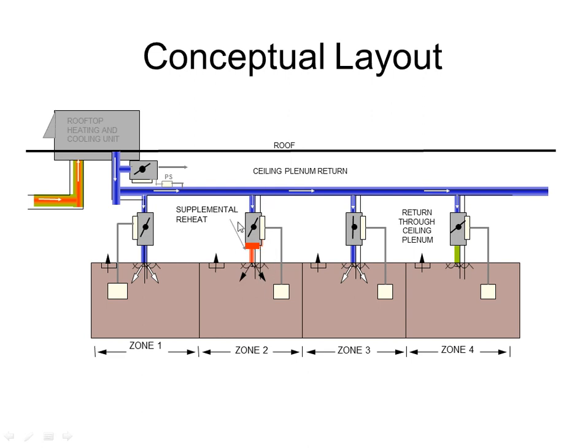And then you can see because some of our zones are close to closed, the static pressure in the duct would be increasing, so our bypass damper is actually open a little bit, not fully closed, and bypassing air. This is into a return plenum. We're going to talk about bypass setup a little bit later, but ceiling plenums are pretty ideal for bypass dampers because it allows for proper mixing of the air. So just a little general 4-zone system, pretty simple. We're going to get into more detail here coming up.